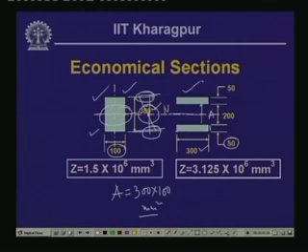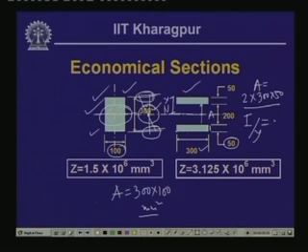Now if we look into the area-wise, we have 2 into 300 into 50. So we have identical area as that of the first one. Now when we compute the moment of inertia I, and then divide this I by the extreme distance, which is y, I by y, we call this quantity as z, which we generally define as the section modulus.